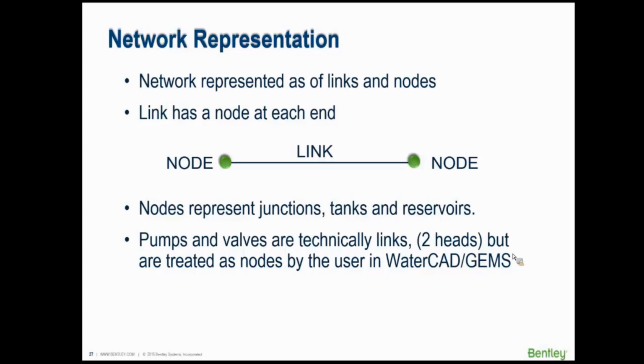The thing about the modeling, though, is solving the head loss equations. For every junction you have in your water system, there is a continuity equation, a mass in equals mass out equation. For every pipe, there is a head loss equation, whichever of those head loss equations you use. So there are a lot of equations. In many water models, we have 20,000 junctions and 30,000 pipes, so you've got 50,000 equations.